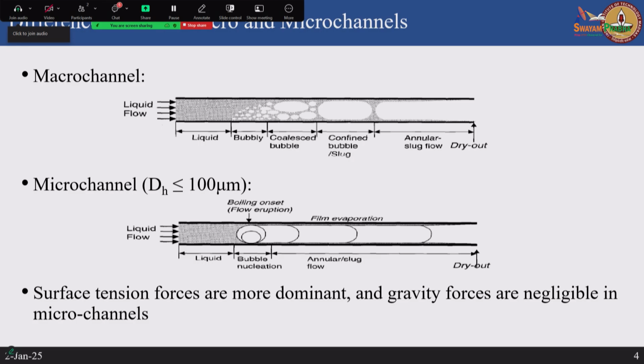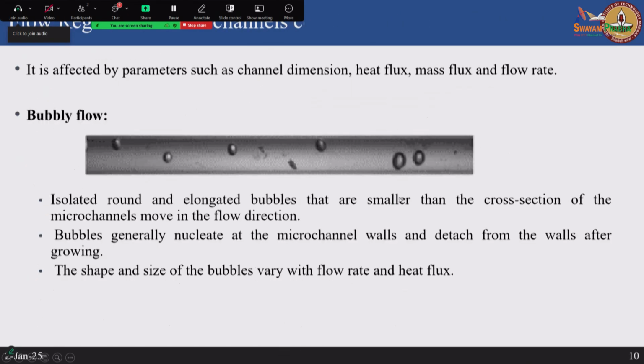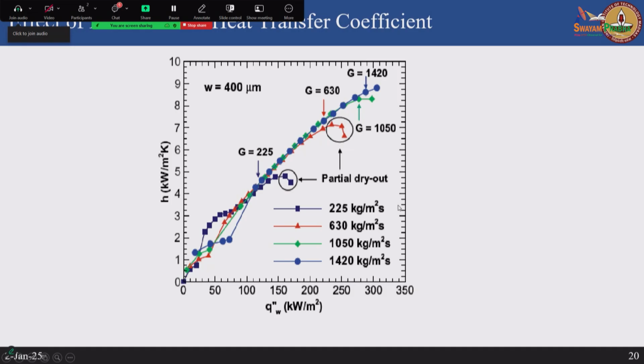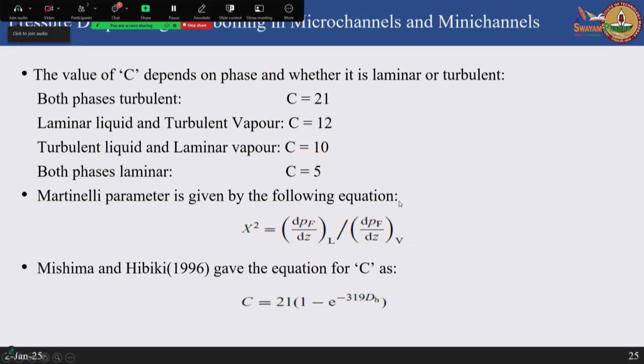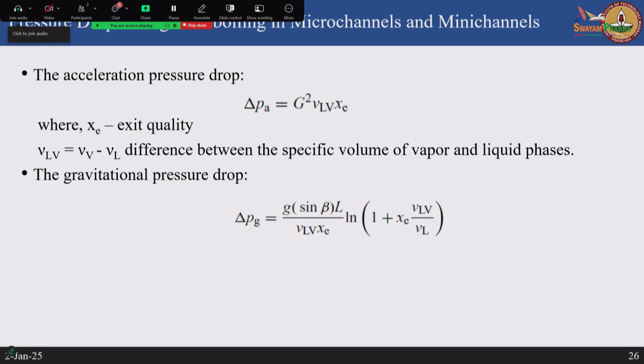Yeah, but there is a term which I have read, but I have not understood, the departure from nucleate boiling, DNB. Yeah, so see, in flow boiling what we do is we plot of course the boiling curves, but also what is important is the vapor quality. So, for example, in the problem that I was describing, your vapor quality is like 0.055 at the exit. So, definitely it is not anywhere close to dry out. By measuring the vapor quality, you will be able to give a more quantitative understanding of whether it is close to dry out or not. If the vapor quality is very large, then you know that somewhere it is going to a dry out state.